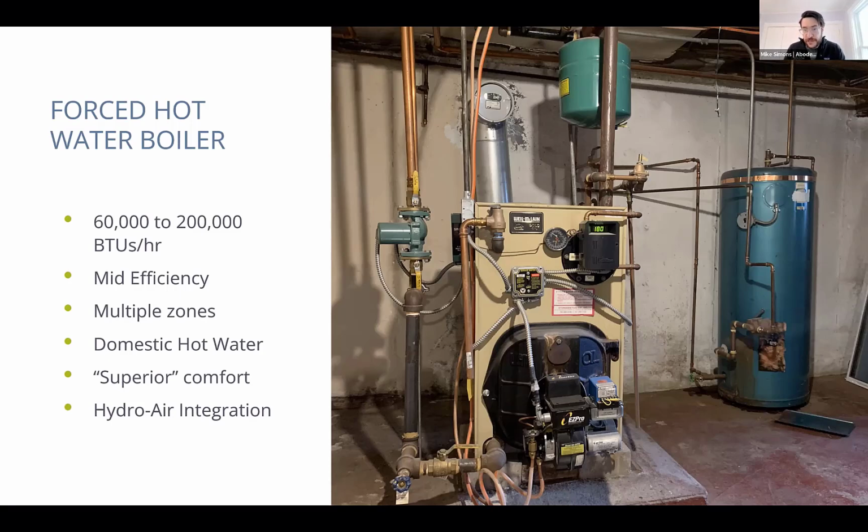Going on to some of the components or controls worth highlighting: with a boiler, they are always going to require electricity. Why this one requires electricity is because there's an oil burner attached to it, and I can see it's wired with 110 volts of electricity. I also see this, which is a circulator pump, and that's going to be pushing and pulling the 180 degree water throughout the home. I also see off of this boiler a hot water heater cylinder, but I don't see any combustion taking place on here.